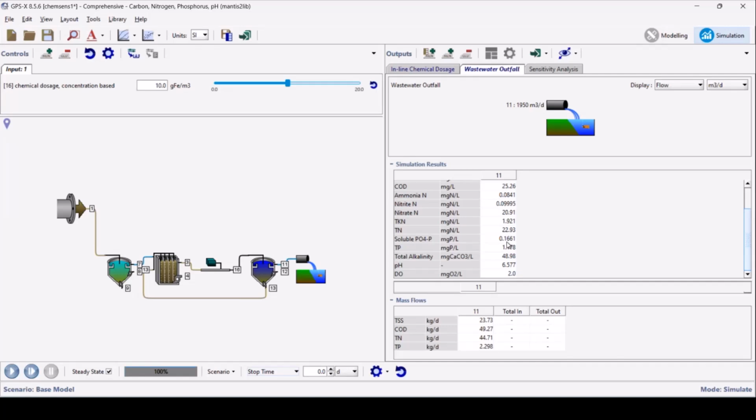These models, of course, are designed such that the efficiency of the next amount of dosage that you are doing is always a little bit less efficient than the one before. So getting down to those lower and lower values, the efficiency of the phosphorus removal starts to drop off, as it does in reality. In those cases, what you'll see is it takes a lot more to get the next fraction of a milligram per liter as you go. Okay, so now we're there.